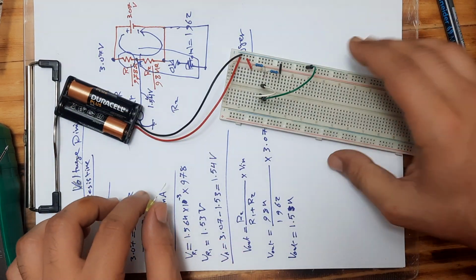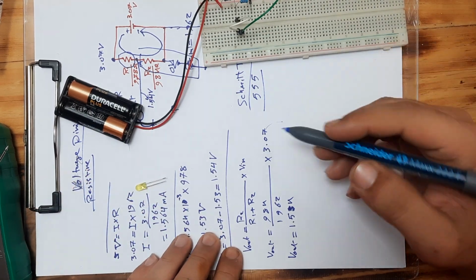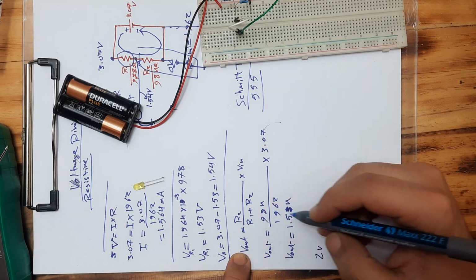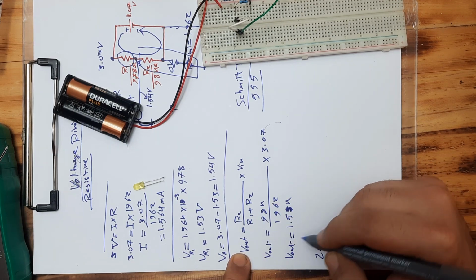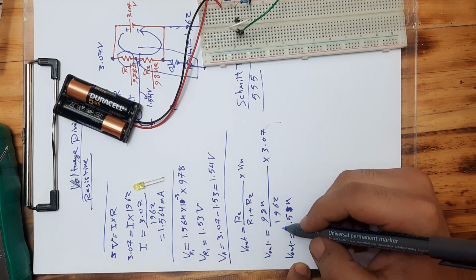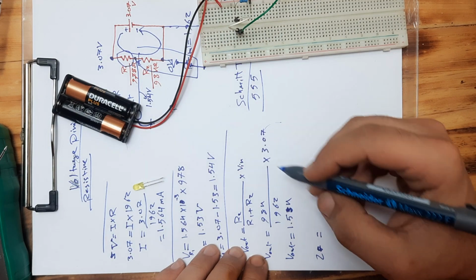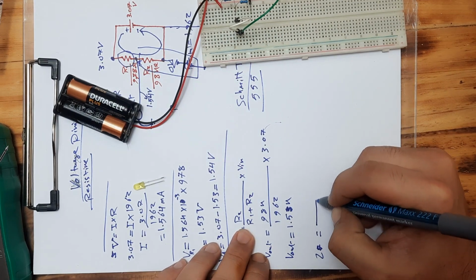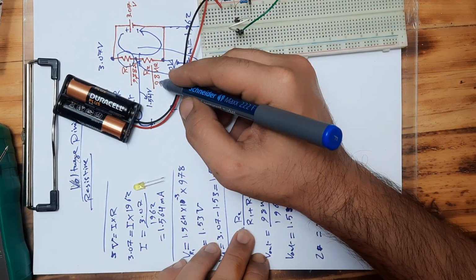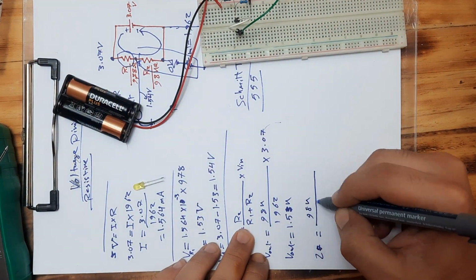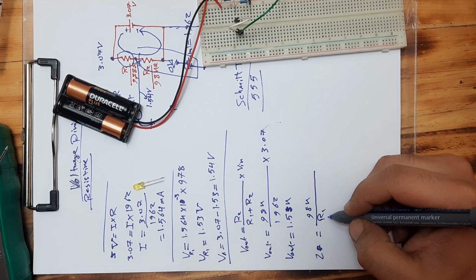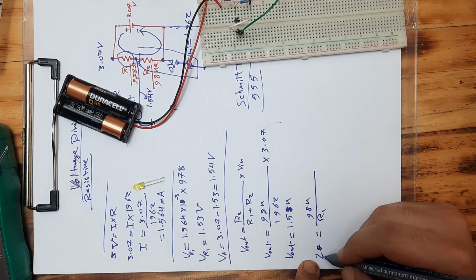We can use this equation. Actually, this is very cool, dear students. Since we want Vout to be 2 volts, we can say, okay, we want the output to be 2, which equals R2 divided by R1 plus R2, times Vin. Let's say we want R2 to be the same as here, 984, divided by R1 plus 984, times the voltage in, which is 3.07, because now we want to select a value for R1 that ensures we have 2 volts.